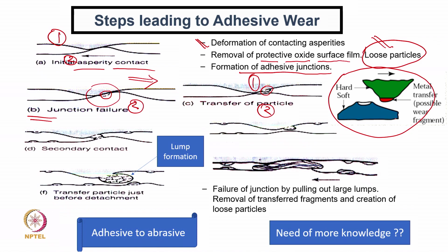If this process continues, what will happen? You are able to see there is some material transfer. Even in a secondary cycle, there is a possibility of some material getting transferred from metal 1 to 2, because of work hardening, and this surface is also getting some sort of deposits. And it moves continuously, maybe for 10⁻³ cycles, 10⁻⁴ cycles, and there will be accumulation.